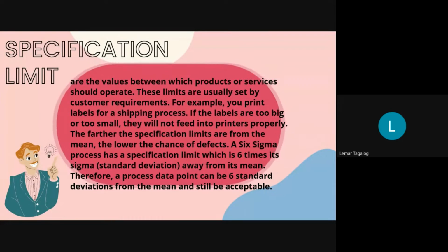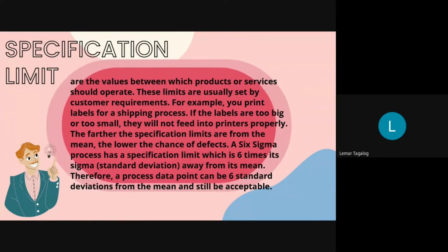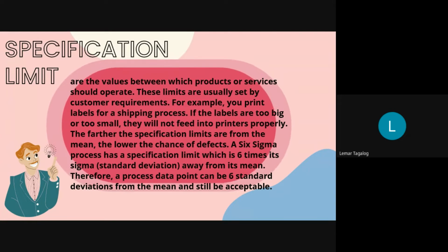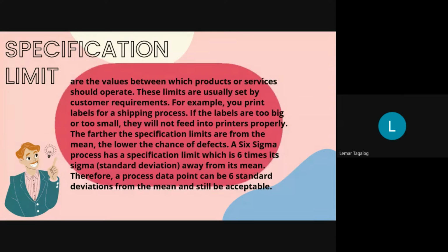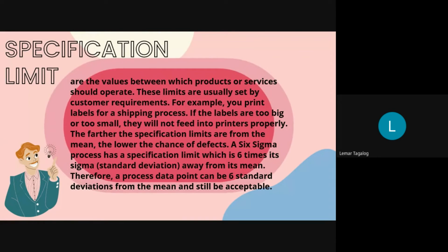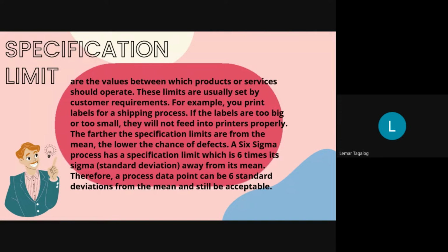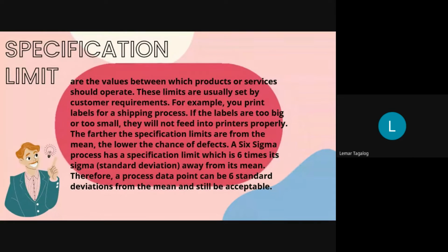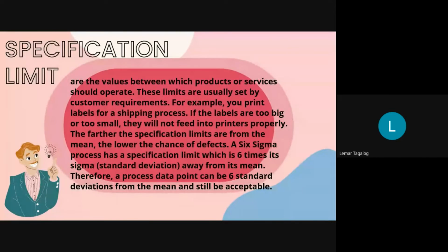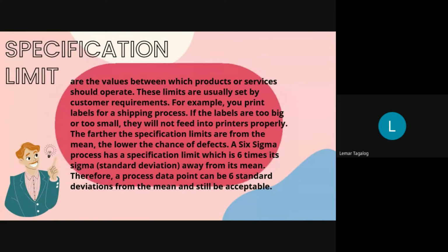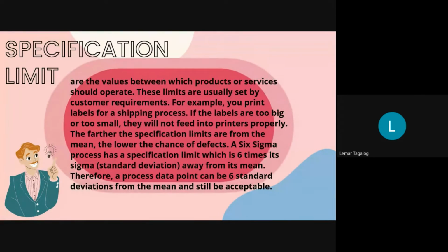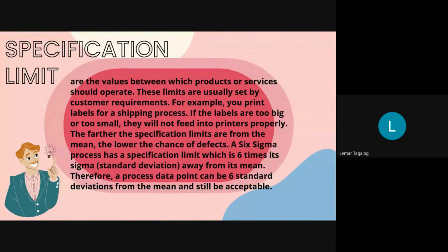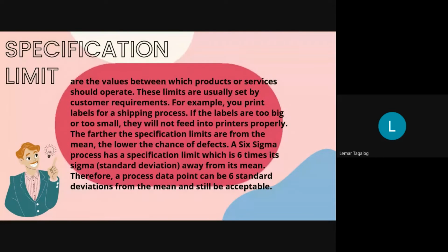Unfortunately, to keep a process in control, teams often develop strategies based on those specification limits instead of ones that better reflect the natural variation of that process. How are specification limits different from control limits? Control limits are calculated from process data. They represent how your process actually performs. Specification limits are defined by your customer and represent the desired performance of your process.